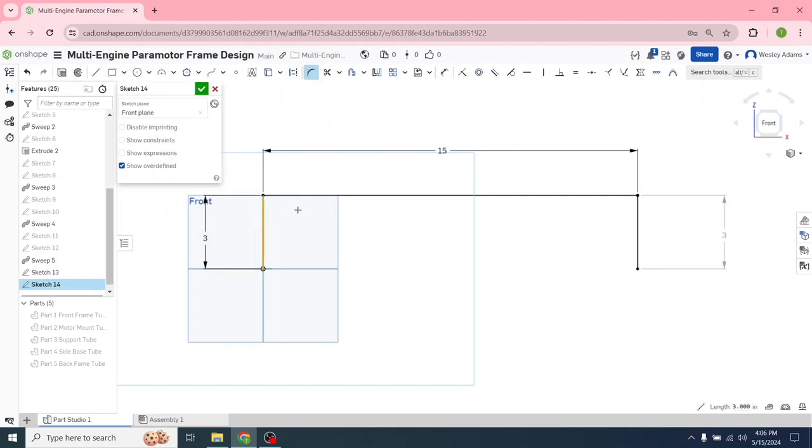Left click on this line, left click on this one. We're going to set the radius of the bend to 1 inch. It's already there. Let's double click on that and just hit enter. Let's drag this down to get it out of the way. Left click here, left click here. I want to take this and drag that around. I like to see that line for radius of the bend. Hit enter, enter again. It moved it around on us, but there we go.